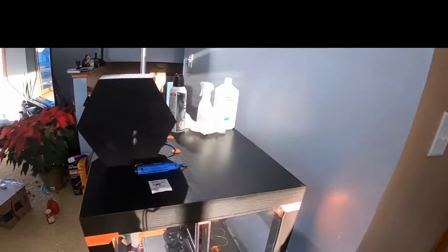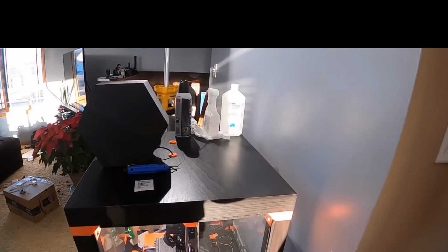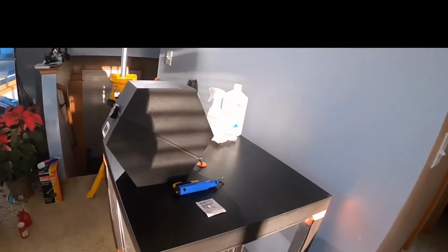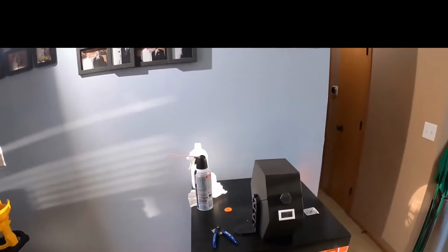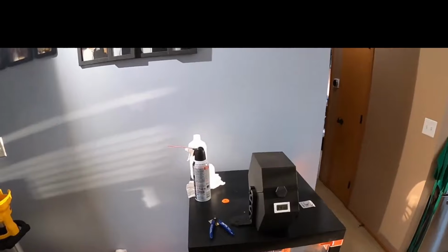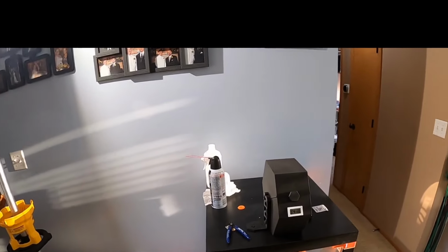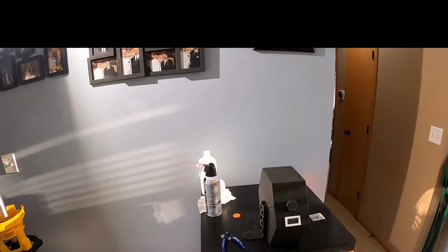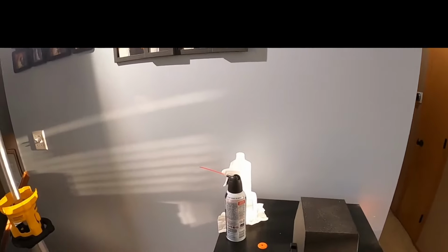If you're printing ABS or PETG, sometimes it'll want to warp if it cools at different rates, and the enclosure helps out with that. And this is just a pair of IKEA tables that you get for $10. 3D printed hardware all around, and then I had the plexiglass cut at a local glass place. And then this is my dry box for my filament.